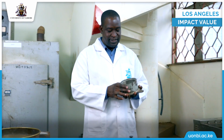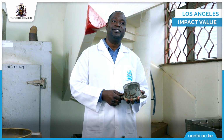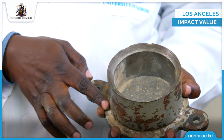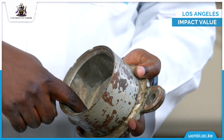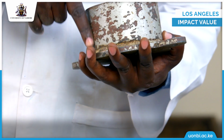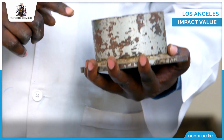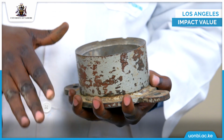So this is the metal cap for placing our sample for testing. As you can see, it has got the external height and the internal height varying. In other words, the internal height is shorter than the external height. And therefore, we have the chamfered edge. The chamfering protects the cap during the testing.